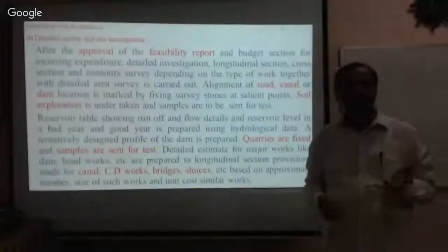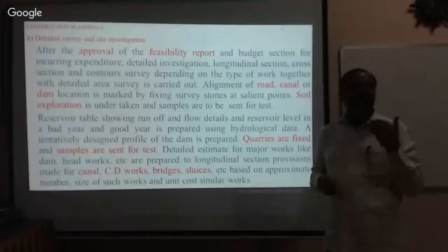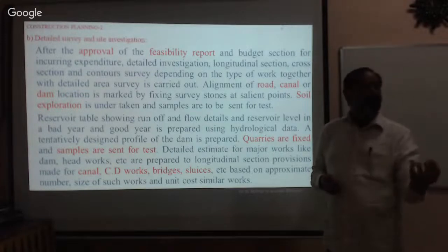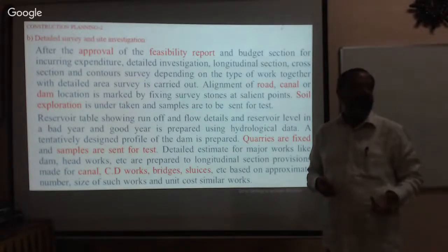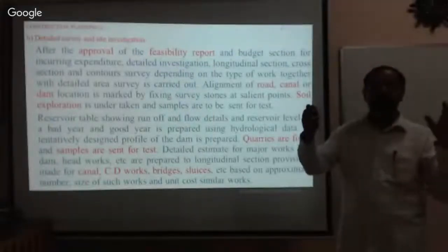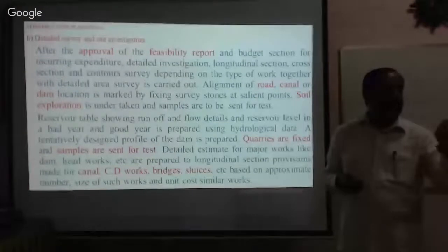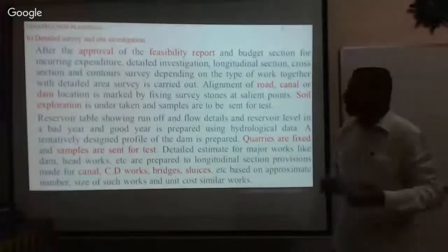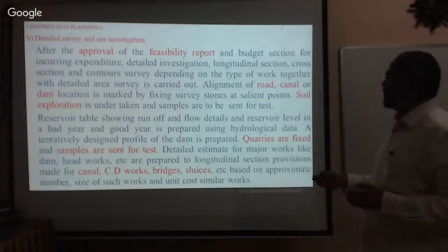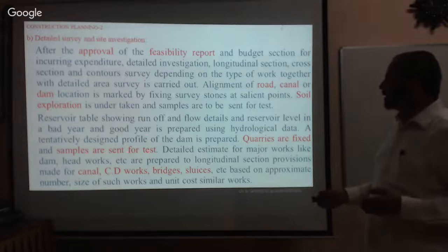While designing the dam, while designing the cross-drainage works, or while designing the flyover, let us be very careful. Ground data is also very essential, isn't it? The soil data is also essential because we have to rest the foundation. We have to keep the structure. So therefore, we want hard soil, isn't it? Therefore, you have to assess this, like soil exploration and samples. Samples are sent for testing.